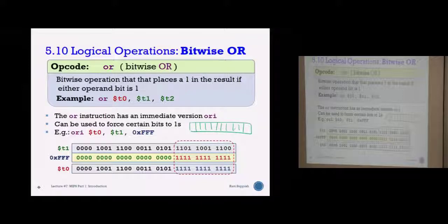Because each bit could represent something. Maybe each bit tells you whether a particular sensor in the system was triggered. So I can say, I always want to look at sensor number 5. Was it triggered or not triggered? Then I create a mask, just look at sensor 5, whether it's 1 or 0. So for the 32 bits, the interpretation is only up to us to define.